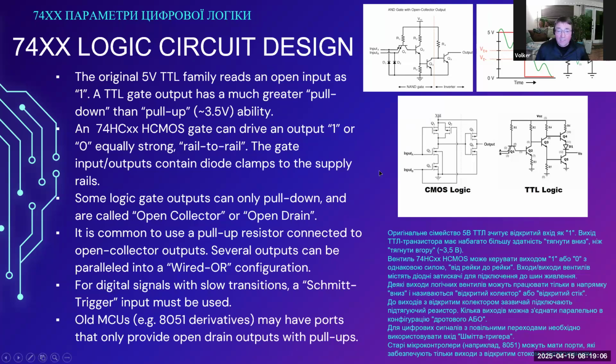There is one important other item that I wanted to mention. In the CMOS logic versus TTL logic display, there is an image shown where you can see MOSFETs replacing the transistors. MOSFETs have a built-in internal body diode, which is not shown in that image.